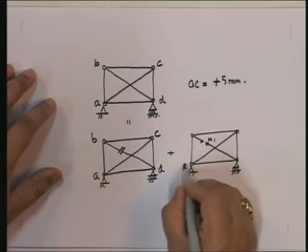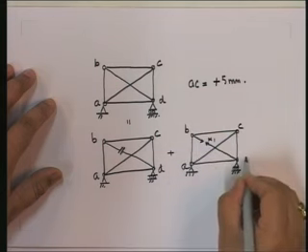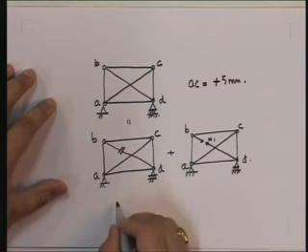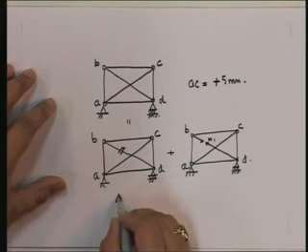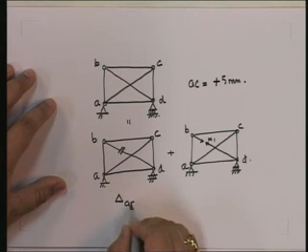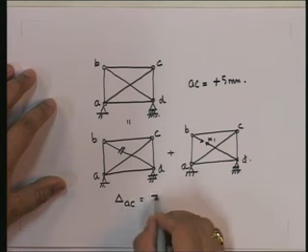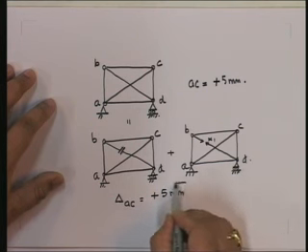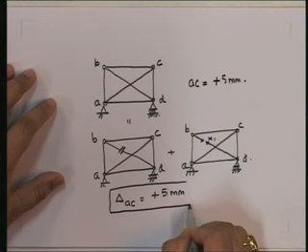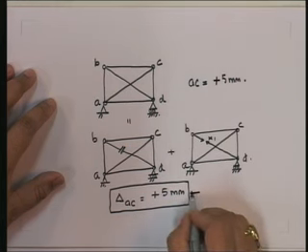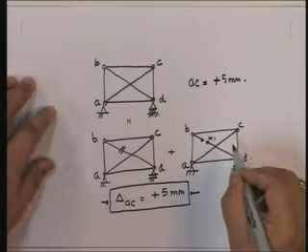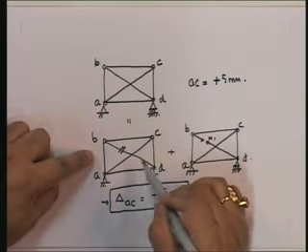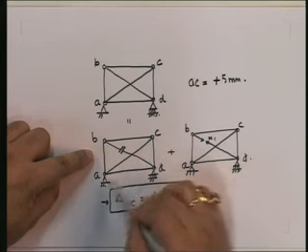And this is how you solve a lack of fit problem. I can say that in this particular structure, delta AC, the lack of fit turns out to be a deformation in member AC. Do you understand what I am saying? In this base structure, none of the members have any forces in them.